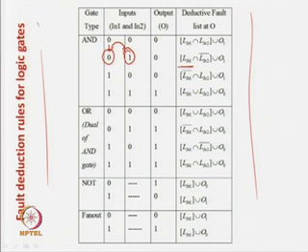So, all the fault list here will be propagated and all the fault list which are here at this point will not be propagated. Then it automatically takes care of the fact that if there is something common between these two, that will not be propagated. Why? Because this input is 1, so whatever is here will be propagated, but if there is something common, that will not be propagated, and whatever fault is at the other input will not be propagated because this input is 0.